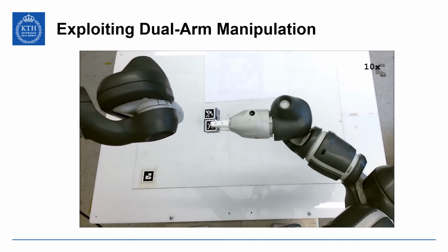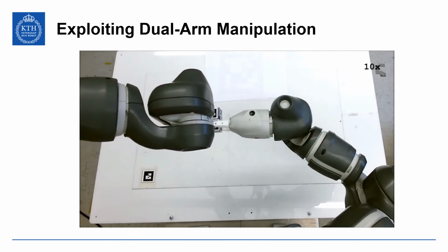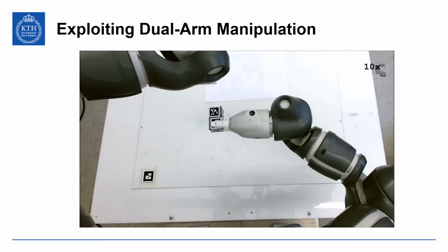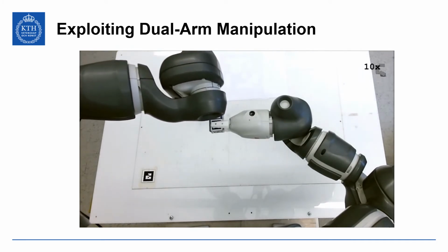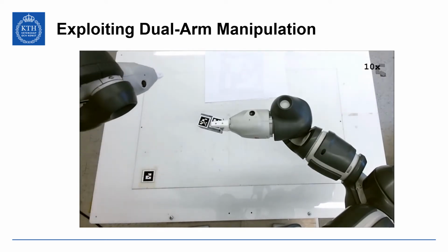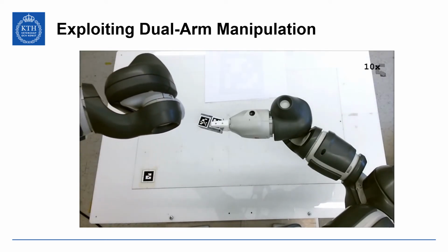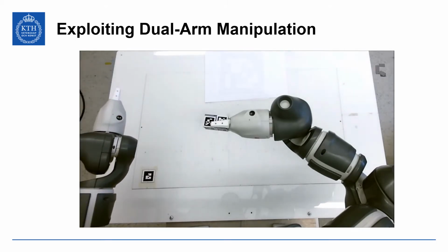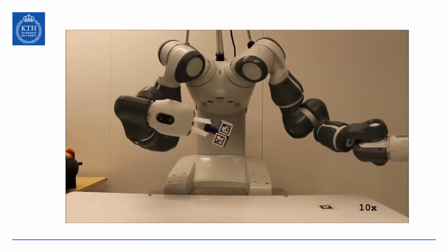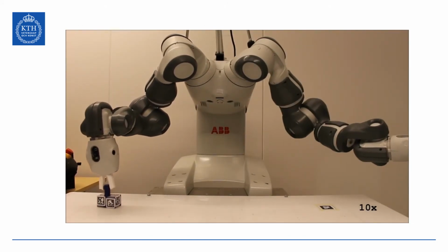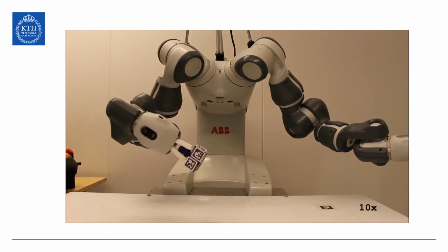In our experiments, we exploit dual arm manipulation to execute the desired motion of the object inside the hand. One gripper pushes the object, while the other gripper is holding a grasp on it. We control the motion by tightening or loosening the grasp while the object moves, and by adapting the relative motion between the two robot arms. However, the same in-hand motions can be achieved also with a single arm pushing against an external contact.